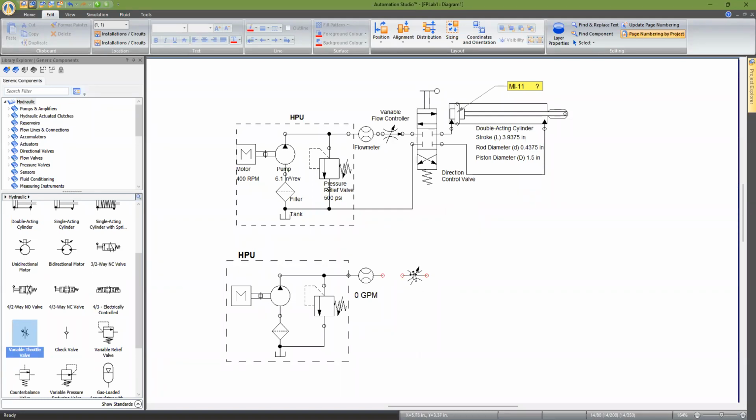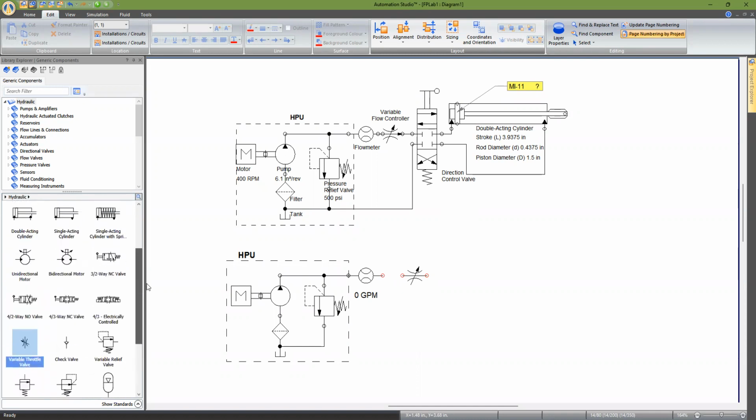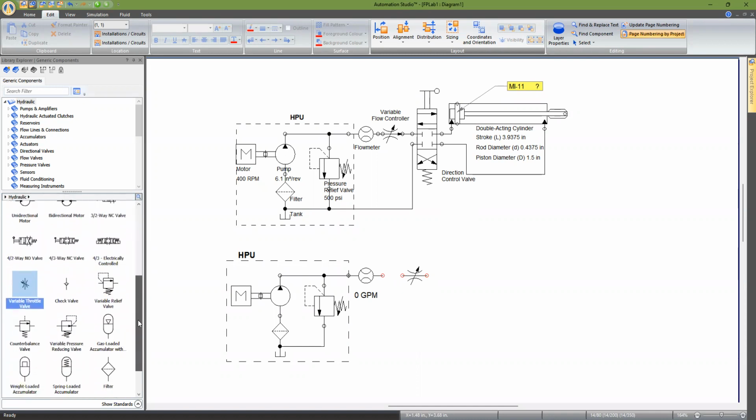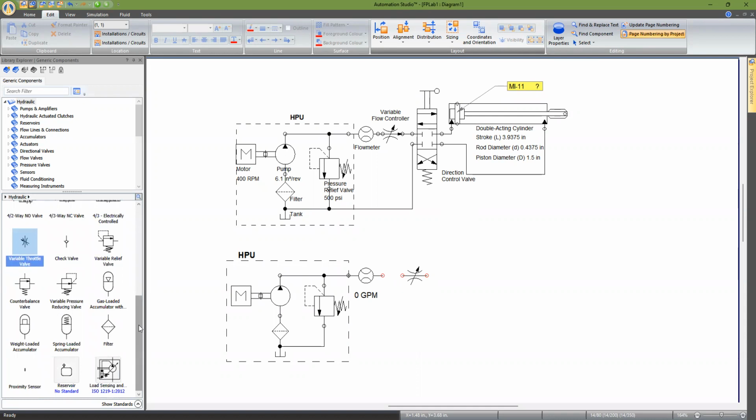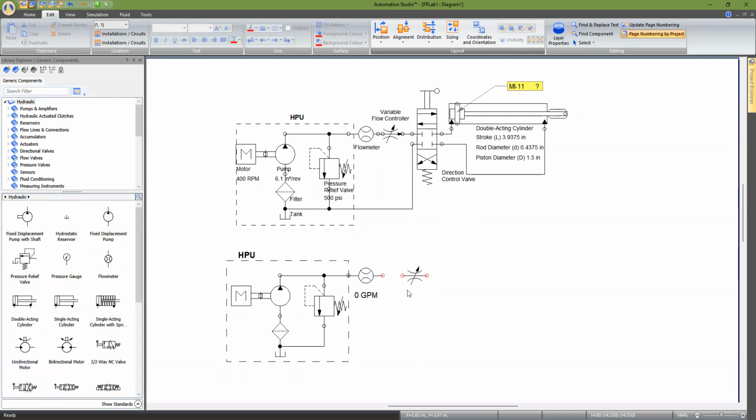But with this one, I have to change the diameter correctly, precisely, to get to a certain value that corresponds to that diameter value. So I will look some more to get the exact one that I need, but that is not available in the home page. So what I have to do, because it's a flow controlling device, is go look for it. Flow lines and connections, flow valves, because it's a valve, I have to look under the right tab. So that's our flow valve.